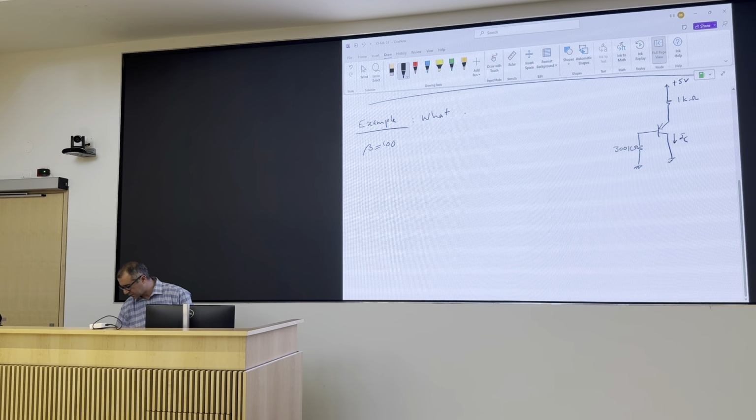The transistor itself, we haven't discussed it much, but beta, we assume 200, but if you look at the data sheet, they usually give you a typical value and maybe a minimum value, but there's no upper value. So they say the minimum is 100, typical is 250, there is no high upper bound for that. It can be 300, it can be 350. There is a lot of variability for beta for a given single transistor. Different currents for the same transistor will give you a different beta. Good news, it's a function of temperature too, right? So there's really no need to get anywhere closer than 5%, 10% of the actual value.